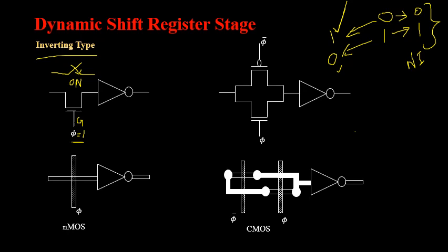Whatever data input I am going to apply over here, say if the input I had applied is equal to logical 0 state, since the switch is closed, the entire data input will traverse towards the other side of the transistor. So here also 0 will appear. This 0 is applied as an input for your NOT gate now. So we know the operation of a NOT gate. When 0 is applied as an input, it will yield an output of logical 1 state. So now the applied signal was 0 and the obtained output was equal to 1. So it is called inverting type.